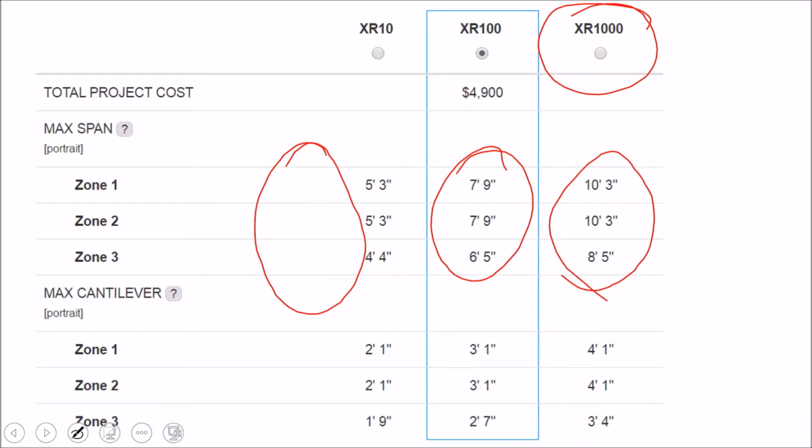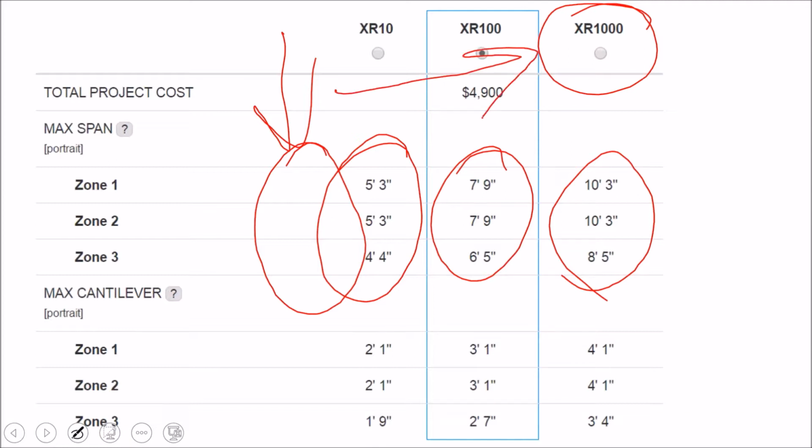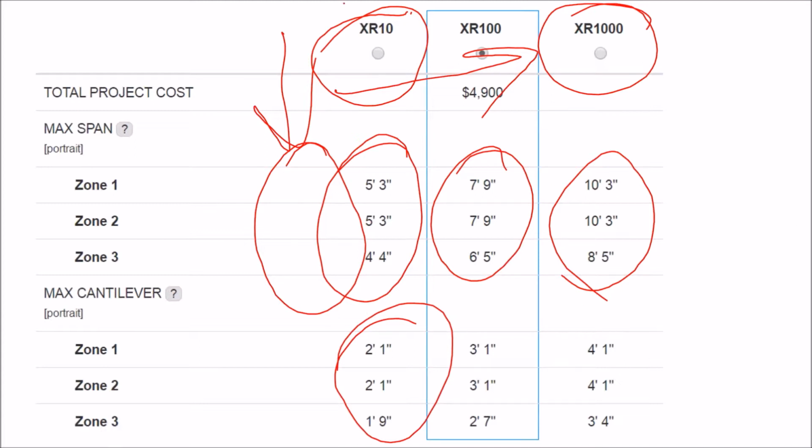And so it might be that if you're going into a 4 foot on center span, which is standard practice, 4 foot on center staggered, or if you're being even more aggressive and going with a 2 foot on center span, you may not need the most robust rail in the world. It might be that you spend more money on attachment points and less money on rail, but you're still going to stay within that cantilever and achieve that hovering effect.